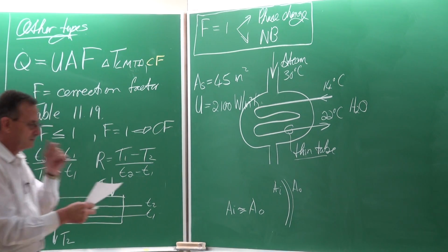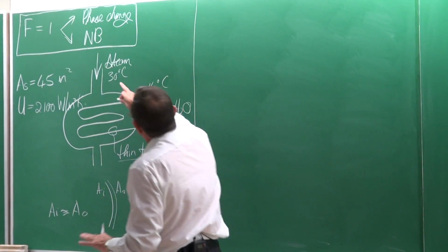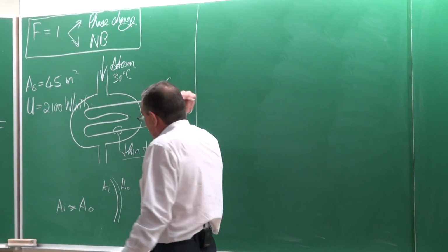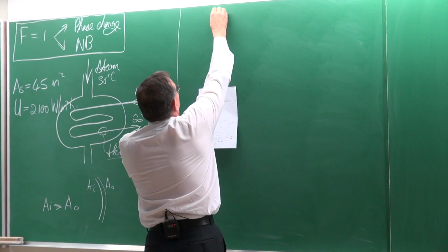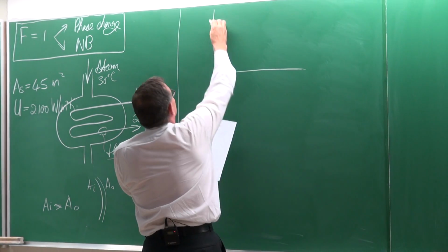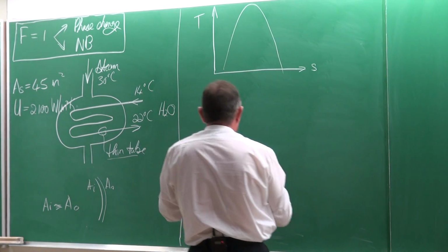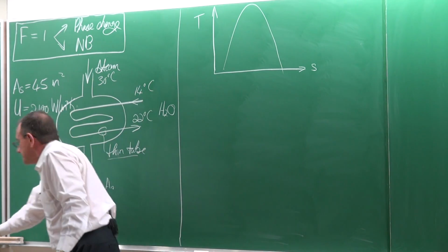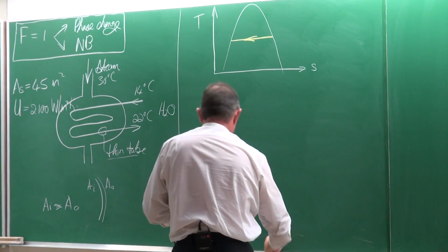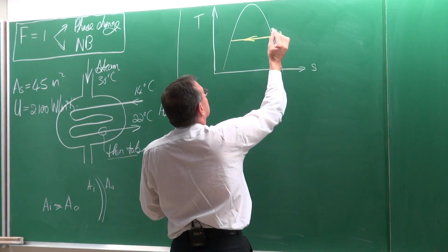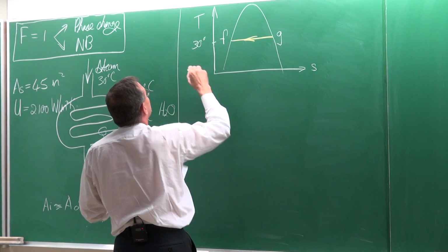Okay. Students also have a problem with this. If they look at this, they say in the exams that, oh, I forgot to give the outlet temperature. This is again something that you need to understand. If you look at the TS diagram, if you've got steam at 30 degrees Celsius, then that is saturated vapor, saturated fluid, and that would be 30 degrees.